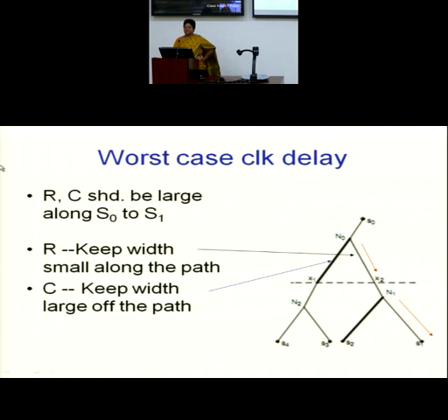Okay, so worst case, as it is written worst case, so can you see that worst case path, this is my on path, so it has a minimum W, but all the off paths, they have larger Ws. So I'm maximizing the delay. I'm going for a situation to maximize the delay. And then I compute. I can compute by using simple Elmore delay model for manual calculations. If it is too sophisticated, you can write computer software. You can use a more advanced delay modeling to compute more precise value through the wire.